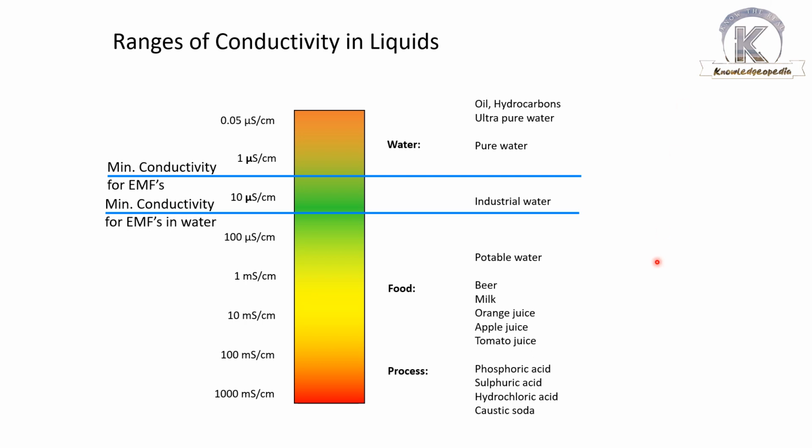That means what? That very small part of the exposed area, that is the electrode, the measuring electrode. If any layer of conductive or non-conductive coating is there, it will finally lead to a reduced flow signal or a more accelerated flow signal. If it is a conductive coating, it will basically create a short circuit, which will damage the flow meter or give the wrong signal level. Okay,